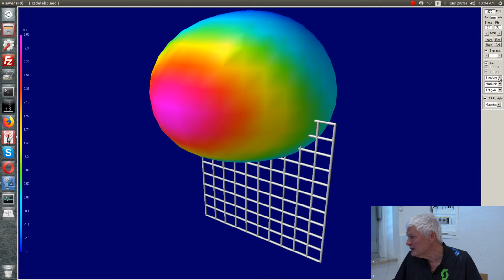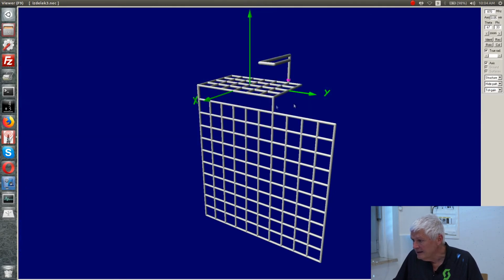So this was our product. We added this connection here. So this was not designed to be an antenna. We just bought a module that had its antenna already attached. But unfortunately, this whole product also acted as part of this antenna and generated a deep zero in this direction. We could remove this zero by just adding a screw to the project.